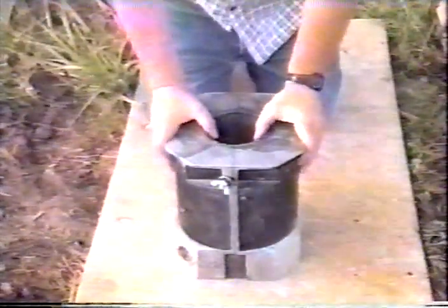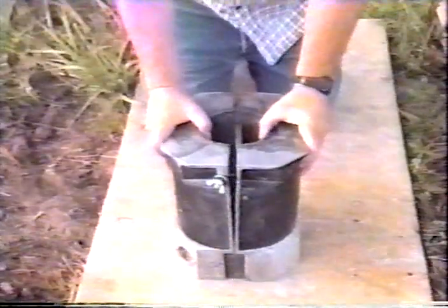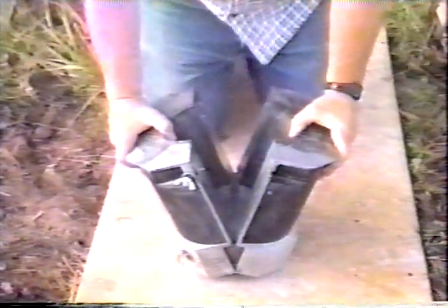TMC is based on casting the test cylinders in special insulated molds that are then maintained at the same temperature as the in-place concrete. This is automatically achieved by a heat controller that reads the in-place temperature through a temperature sensor, a thermocouple, and adjusts the temperature to match the readings.